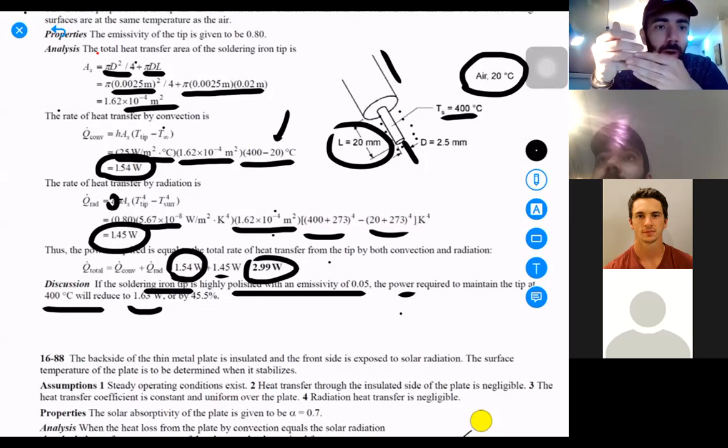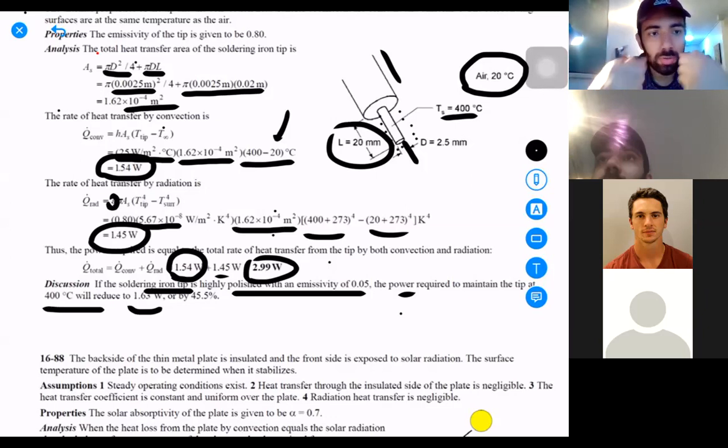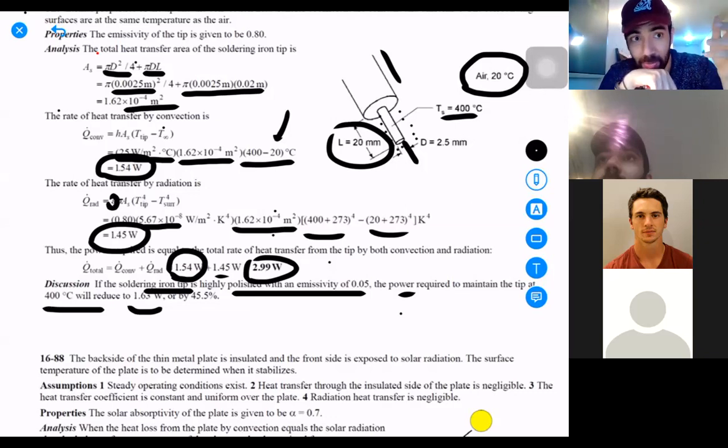That is how you will reduce the amount of energy you would consume for keeping the temperature of the surface you are working with. And that is why in many cases the convection term is much higher than the radiation, because we always try to reduce the emissivity constant in a way that a good share of the radiation term would be decreased with respect to convection.